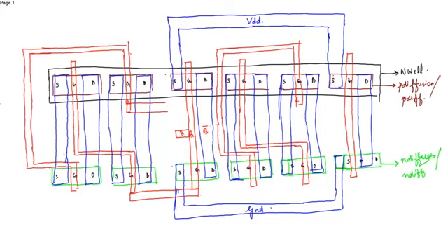So it's poly and metal overlapping. So this is B bar and this is B. So we need a poly contact now. Poly contact is placed over here. Just marking. This is the poly contact. To do one thing, we can just shift this, erase this area.